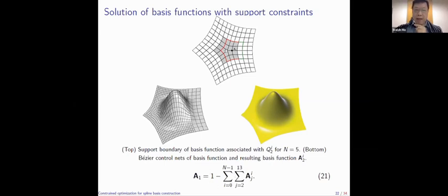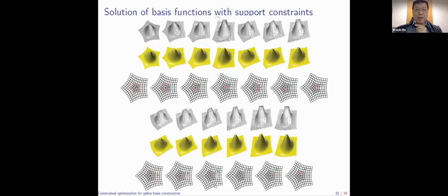So finally, the center basis function is produced by this equation for producing the partition of unity property. In any case, all the basis functions are piecewise Bezier, actually piecewise polynomial, like this one for A2. And all the bases have the POU property. Here you see all the basis functions for valence n equal 5. We have solved for n up to 9.